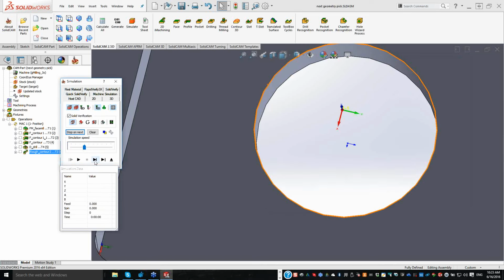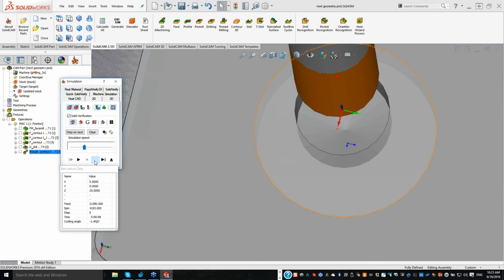Now, it's going in through the center. However, note, when it gets to Z level, towards the bottom, to do the helical entrance to the floor, there's really not enough room for any kind of clearance over here. This is too small of a circle to already start helical down into the part itself.